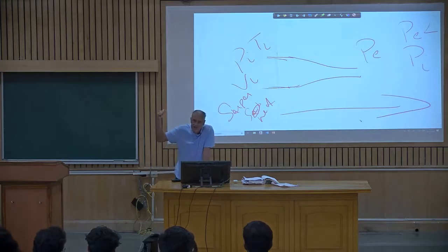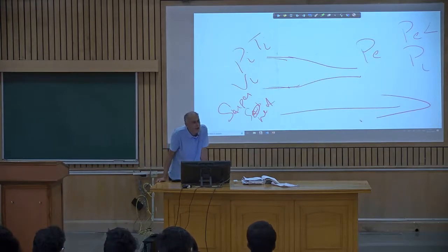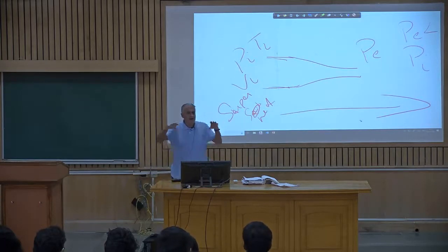So there's a delta P coming from your main valve. And when it hits a restriction, it accumulates pressure here. So what happens to delta P? Goes down. So it's not just about the velocity going up. What happens to the pressure gradient? Goes down. Now you know where I'm getting to with the hint I've given you. P exit is lower than P inlet. So you're losing pressure, yes? You're losing pressure gradient. So what is happening to that superheated vapor that's coming in and hits a little bit of geometric change? Its gradient begins to decrease.